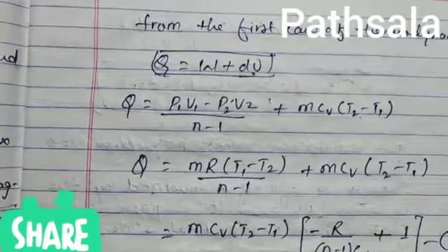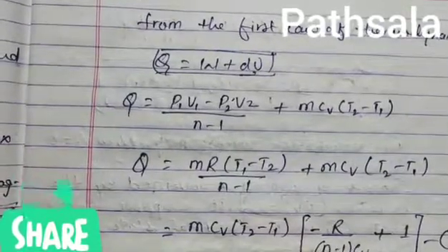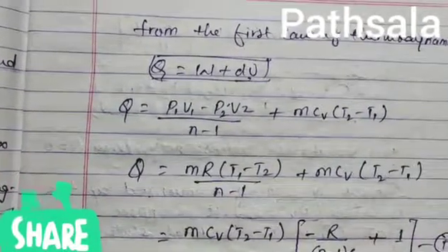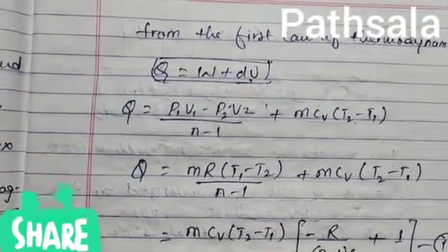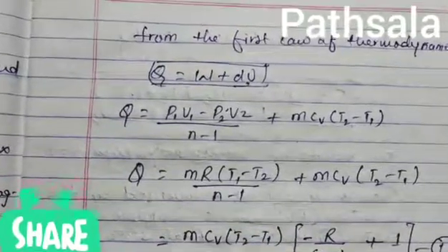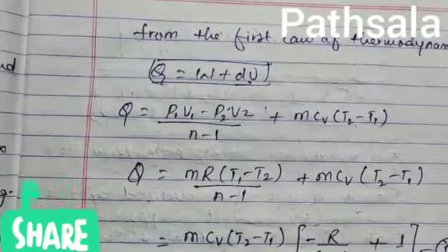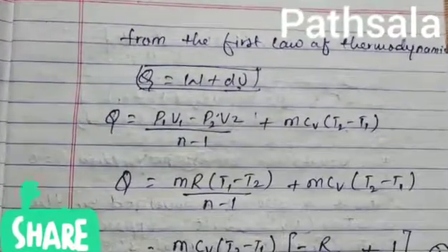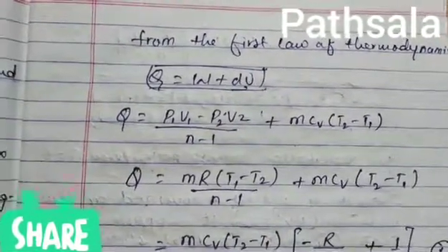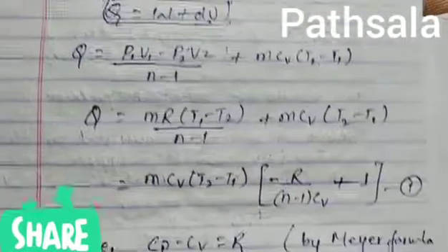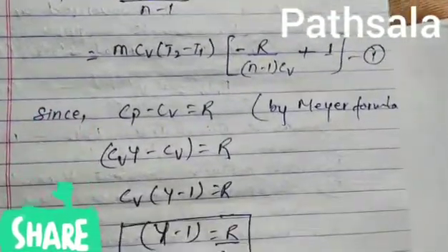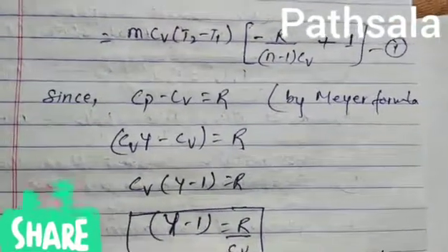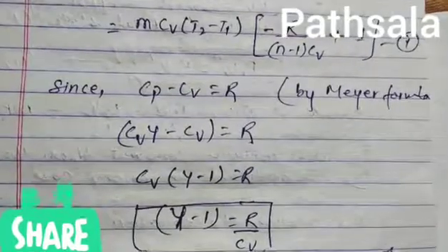Now we find the work done in the reversible polytropic process. According to the first law of thermodynamics, Q is equal to W plus dU. That is, heat supply is equal to work done plus internal energy. Q is equal to P1 V1 minus P2 V2 upon n minus 1, plus internal energy, which is m Cv (T2 minus T1). As you can see, Cp minus Cv is equal to R by Mayer's formula, R is the gas constant.